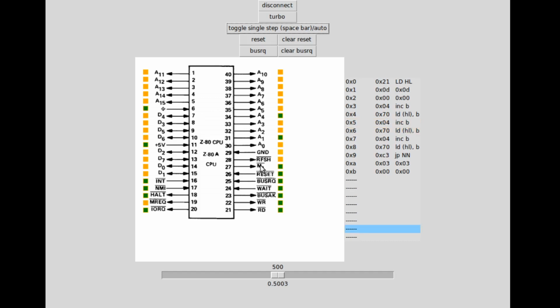So what do we got going on? These are two outputs from the Z80 that tell it what kind of memory fetch or write it is doing. Well, no, fetch, I suppose. So M1 tells us that it's the operation, the operand that it wants to load. So load or increment or jump. And when M1 isn't low, then it's either a refresh read or it's loading, I don't know what you'd call it, the bytes that come after the operator.